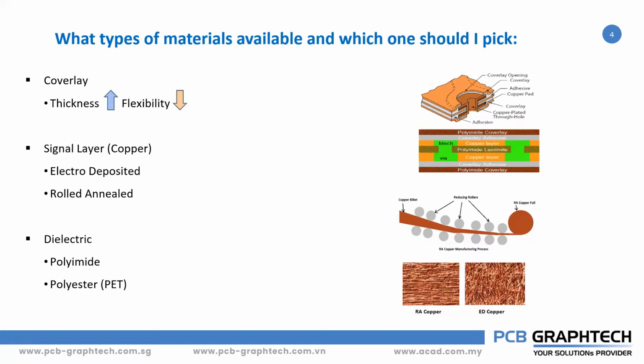So we have so many advantages for polyimide material, but we need to consider it is a little bit expensive compared to polyester. Polyester is very cheap, but it is not heat resistant. It is also less in weight, so it cannot be handled under high temperature. So it is based on your design, you need to consider the material. It doesn't mean that because I say polyimide is tough and very good but expensive, you must use it. Based on your design, you can choose your materials.